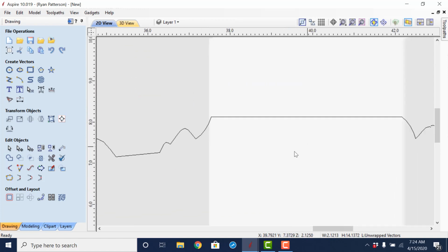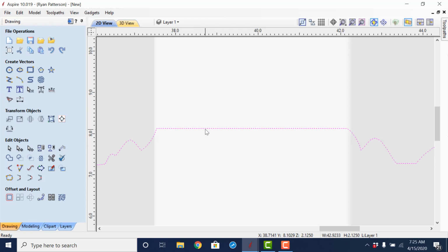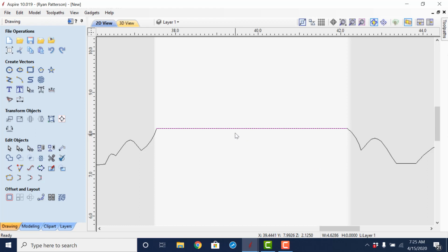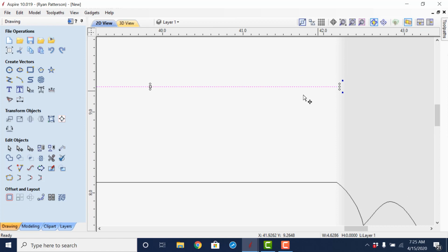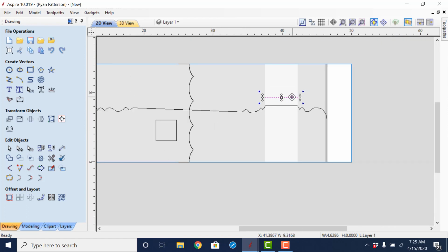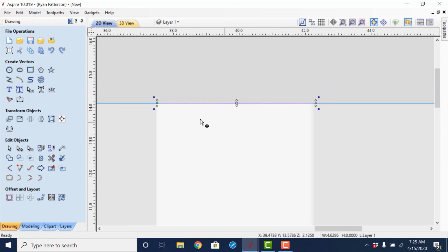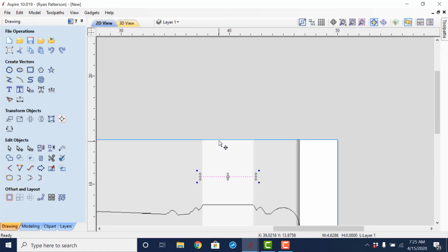The next thing that we need to do is create our rail sweeps, the distance for the top and the bottom. And to do that, I'm just going to draw out a line from that distance right there, selecting that line, and I'm going to move that up to the top of the job. We'll do a Control-C, then a Control-V, which pastes that, and moving that down to the bottom.